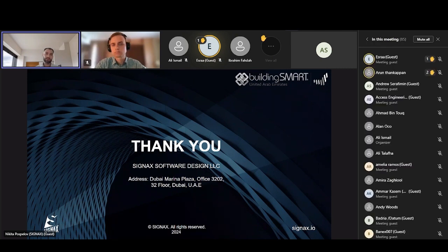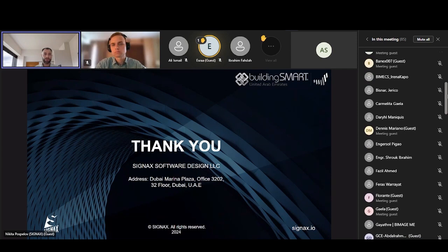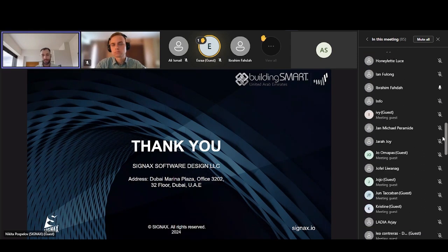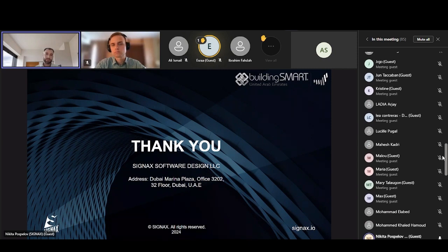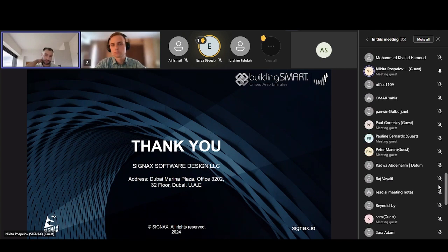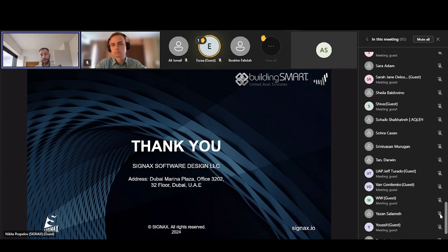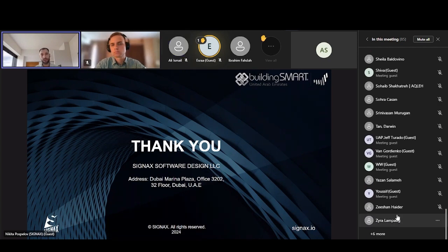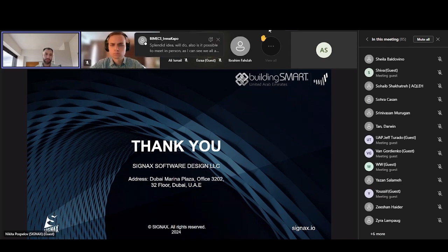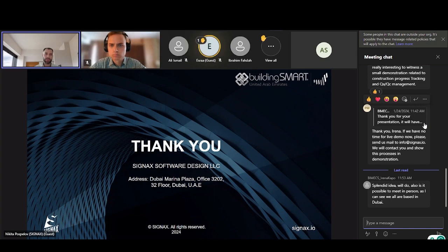After that, the lead consultant was responsible for overall model coordination. If some issues were found, we created issues inside the CDE system connected to the BIM model files. The subcontractors were then responsible for fixing these issues, answering the issues inside the cloud system, and uploading updated BIM model files. Every workflow was strictly tied to deadlines. For example, each subcontractor had one or two days maximum for the correcting process because of the limited time of the project. After that, the lead consultant once again checked the fixed information, and if everything was okay, it was passed on to the construction site.